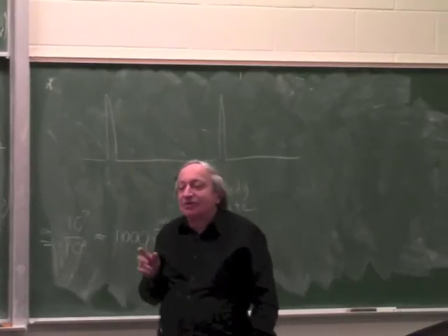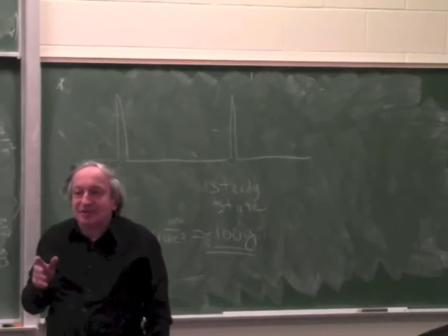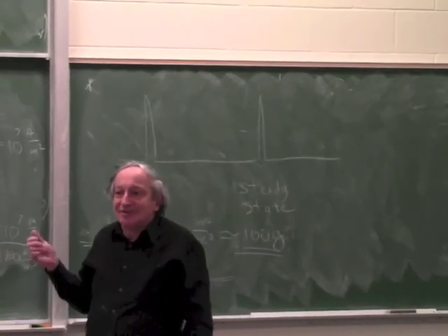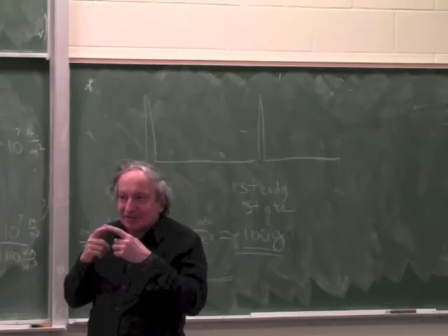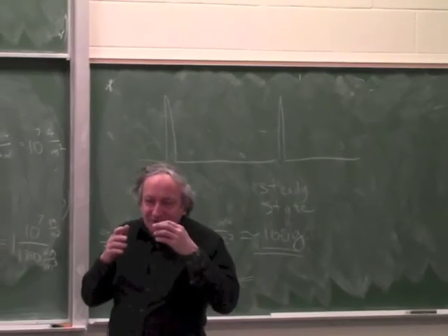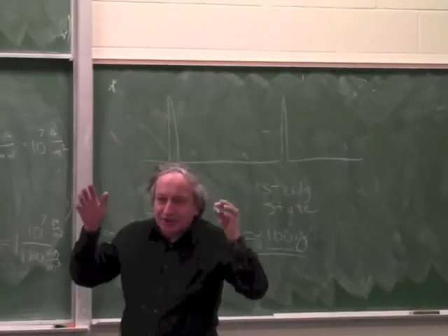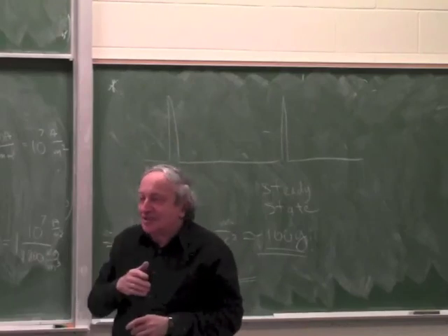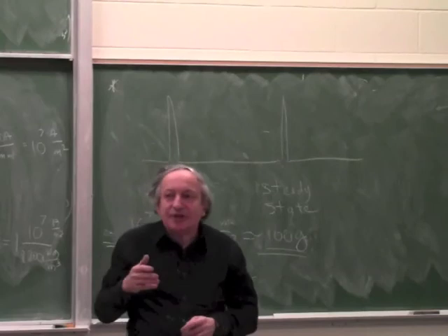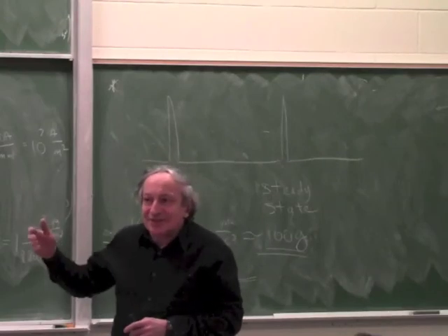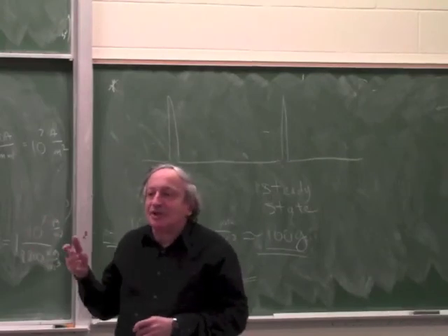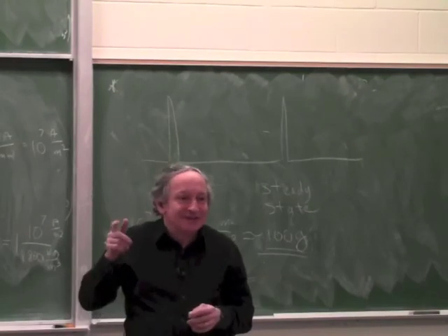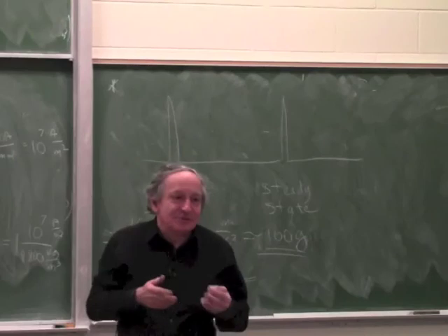By the way, I cannot make the coil without impedance, because a coil without impedance will also generate no force, because they are theoretically linked. If you think about it in a bigger picture, the force is the derivative of energy with respect to distance, and the energy in a coil is 1/2 L i squared. So if I can make a coil with no impedance, it will also make no force, because it will have no L, and then the derivative of the energy with respect to distance will be 0.